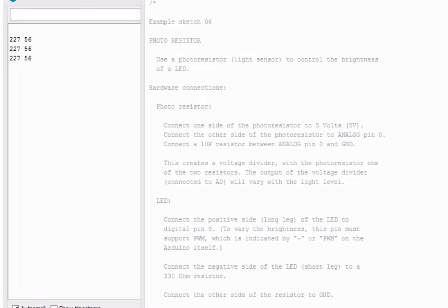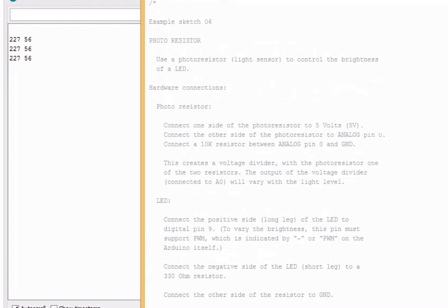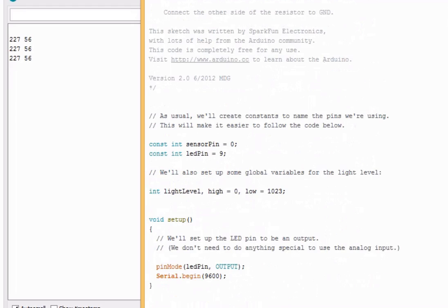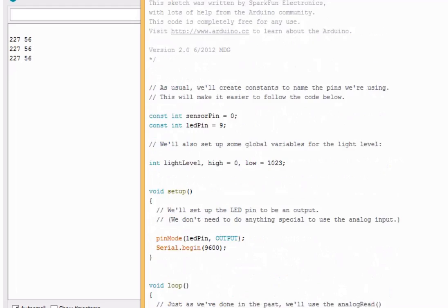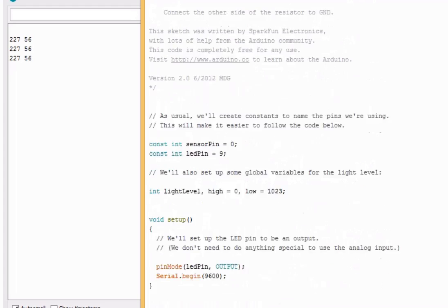As we head over to the sketch, you'll notice I've got a little bit of the serial window poking out to the left side of the actual sketch window. I've made a few modifications to the sketch that I was given because I was having difficulty tuning the photoresistor outputs to actually be something visible and to match with what the program was attempting to be saying. So I've added a few commands in order to give me some serial output to see what the actual read off the analog pins is and what the output it's giving is.